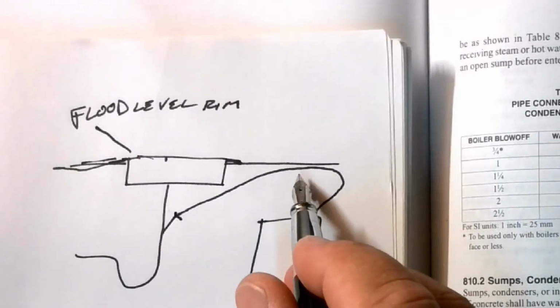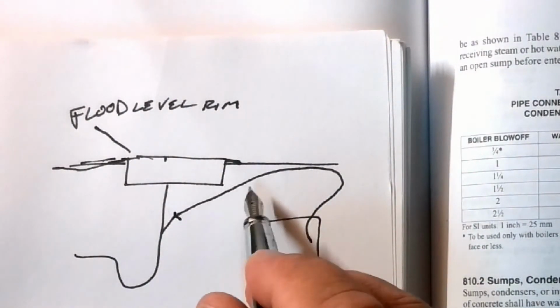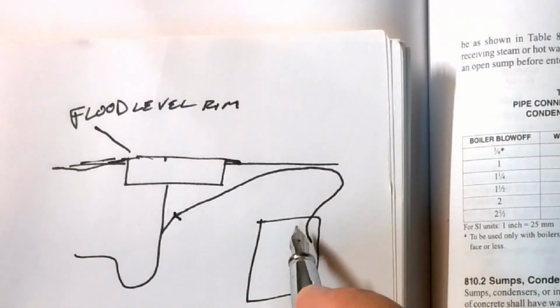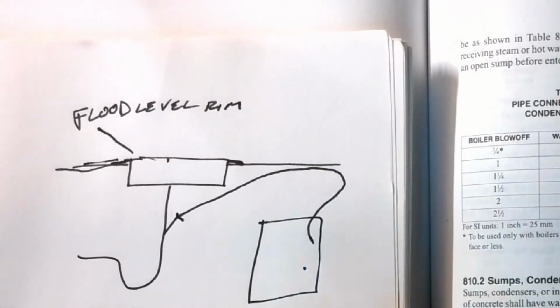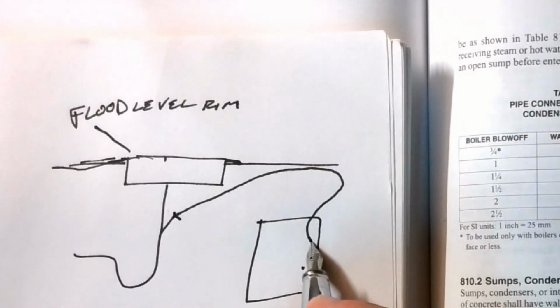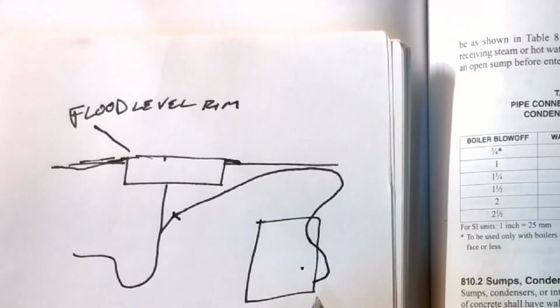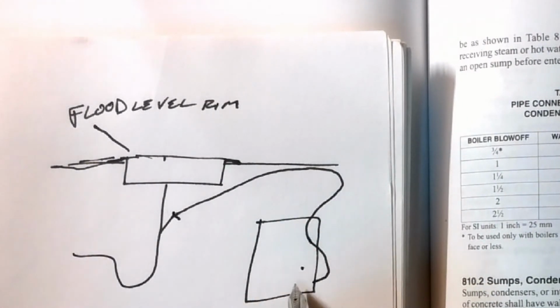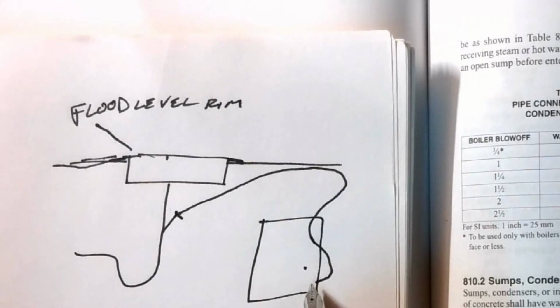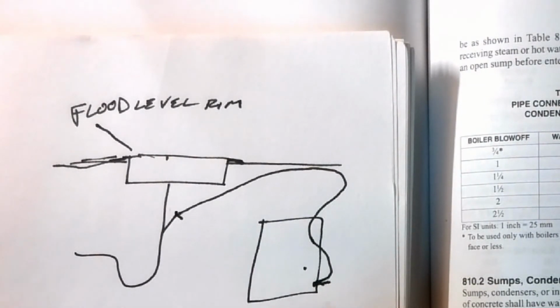Well, there's no air gap here. So this is going to come up, raw sewage is going to come all the way back into here, and it's going to come into this dishwasher. And that's really gross, okay? But then the manufacturer's argument is going to be, well, we have an internal check right here, and it's going to be fine. Well, guess what happens if this dishwasher runs, and most people don't sit there and clean out their internal check. What if some kind of grindage or material got in here and forced that little internal check open?